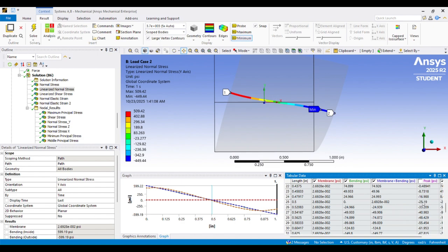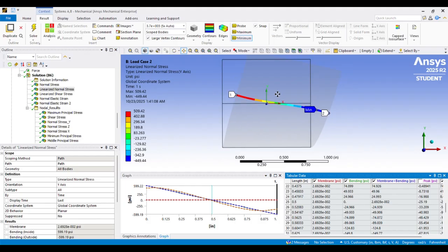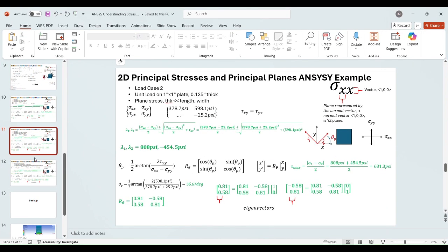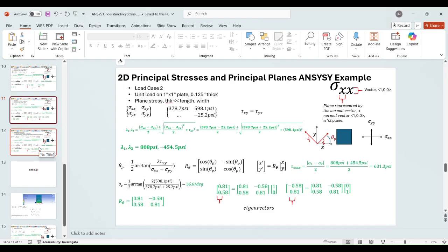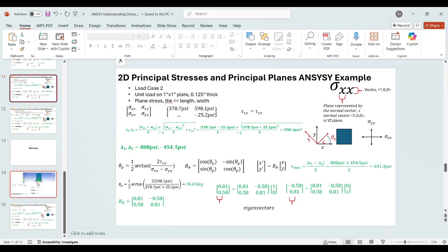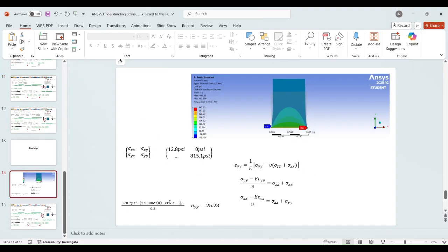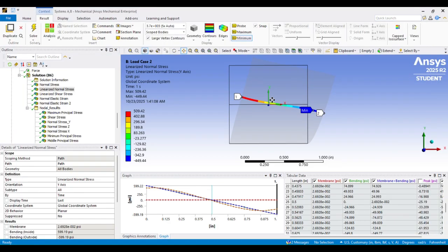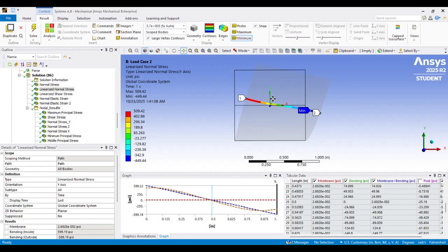But we have this stress, and so I went through this and actually calculated it. And again, that's related to the fact that we fixed the bottom, and the part wants to contract and it can't. So I actually pulled the strain from the model, and I went through the Poisson's calculation, and I got this stress result. So we're seeing a slight compressive stress because of the way that the part wants to contract from the loading, and it's fixed.